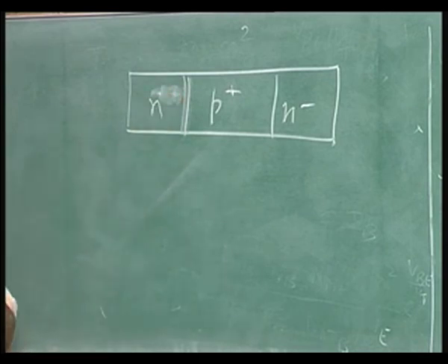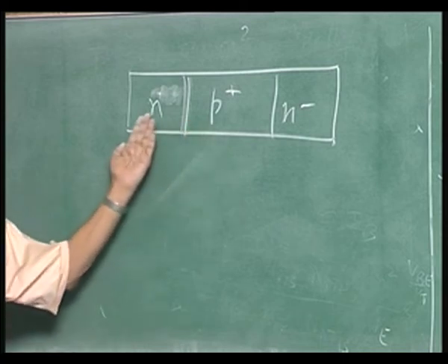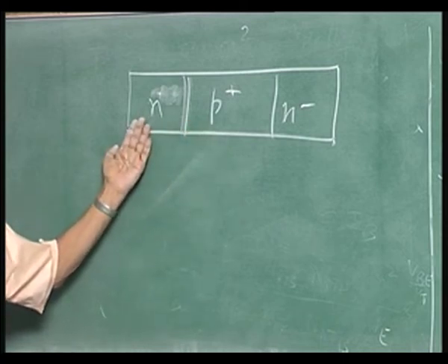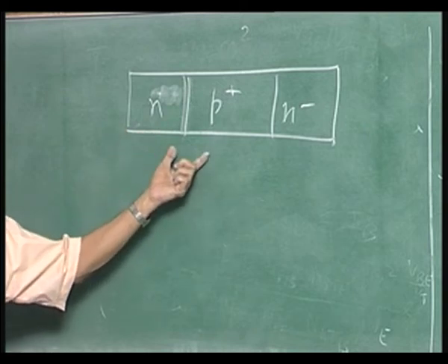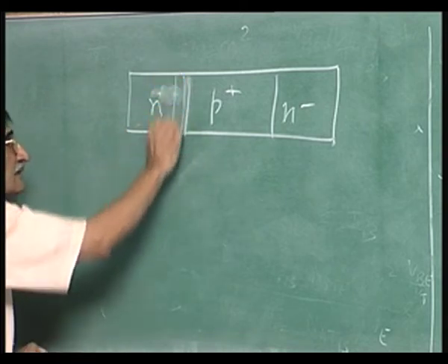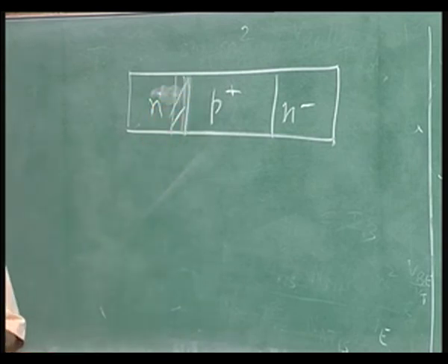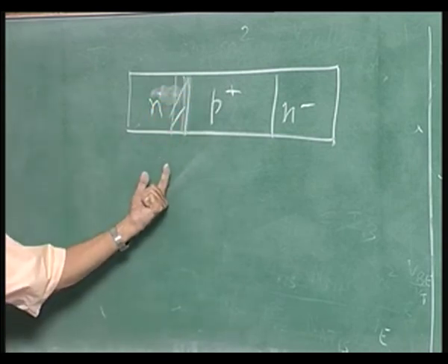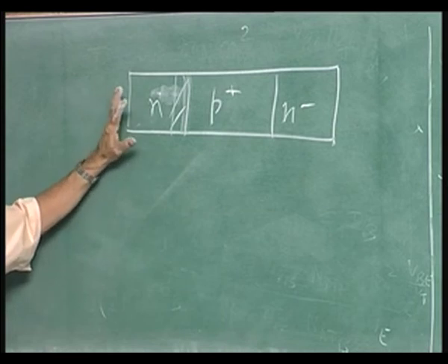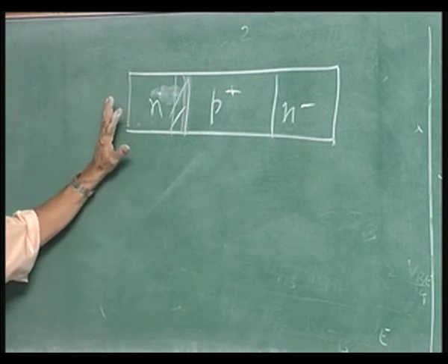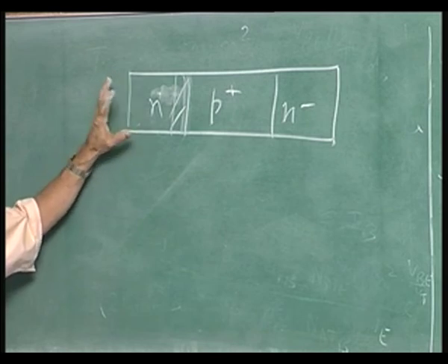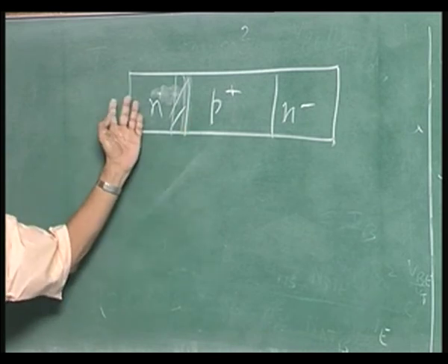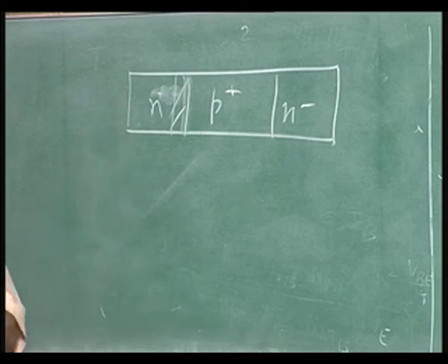Now, you see the whole thing is reversed. Base is doped much more than the emitter. Total integrated doping in the emitter is lower than the total integrated doping in the base. I can have this depletion layer going up like this, wider depletion layer, CTE will go down if I am able to decrease the doping. But my worry will be, if I reduce the doping here, if the band gaps are same in the two regions, emitter efficiency will go down, you will get a very poor transistor.